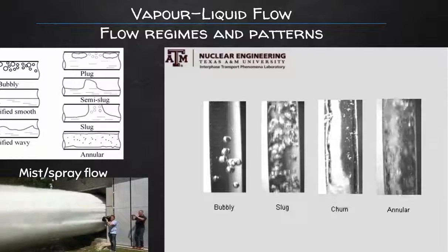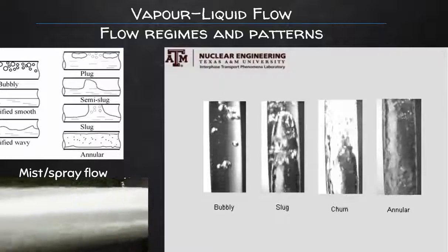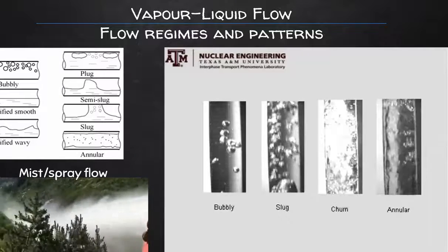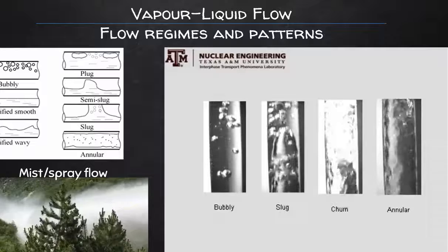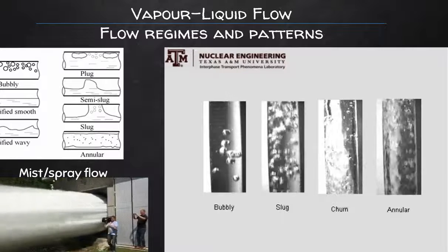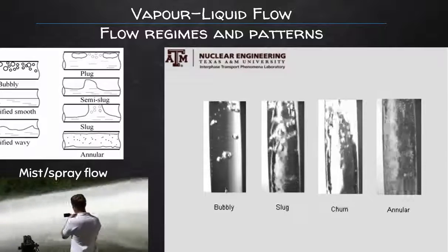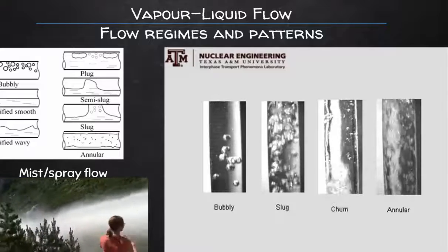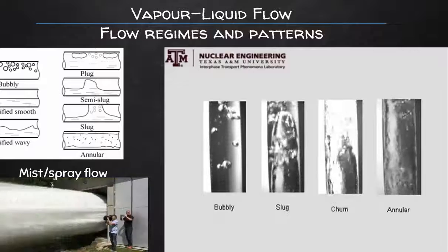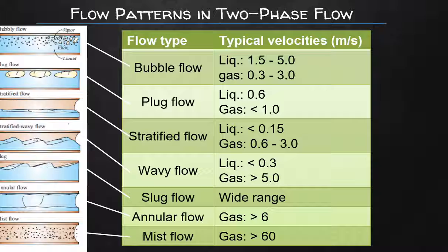Now, in the case of vapor-liquid flows, I would definitely not like to be a fish or turtle. This type of system is characterized by various flow patterns, specifically bubbly, slug, churn, and annular, and also mist and other things, and some other possibilities can arise, and these are dependent on whether the pipeline is horizontal or vertical, and what type of fluids you are working with.